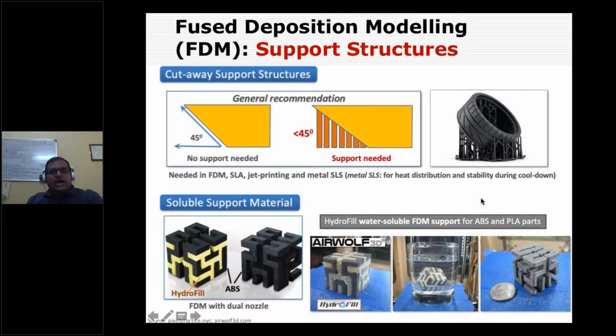Anyway, you are going to have some hands-on with the Cura software, and almost all these capabilities will be there in Cura. You can vary the infill density, so you can do several things. Utilize that Cura assignment properly and explore all these features in Cura. It is free-of-cost software, which I hope everybody has installed on their PC.